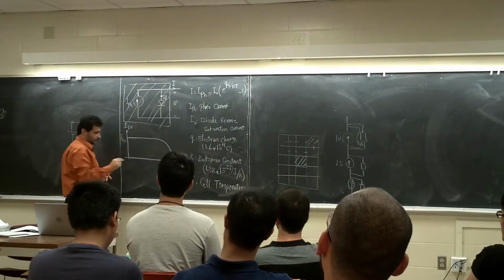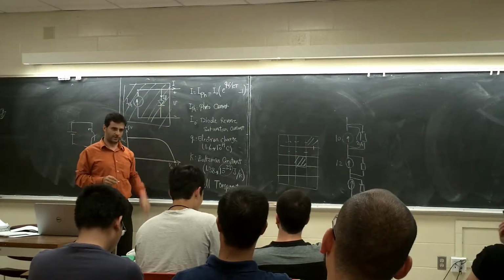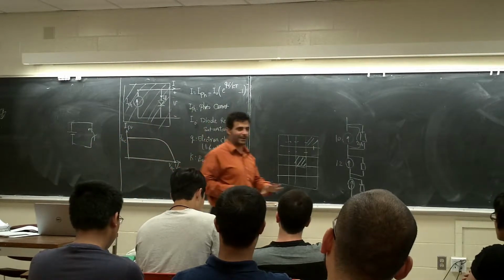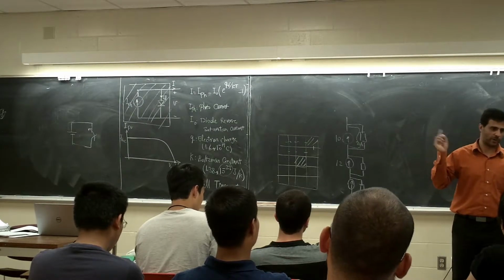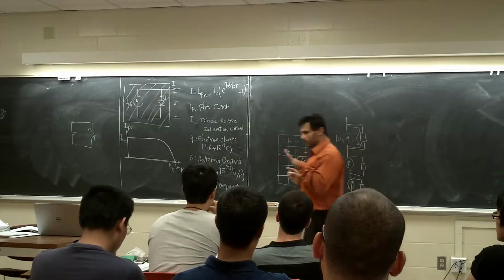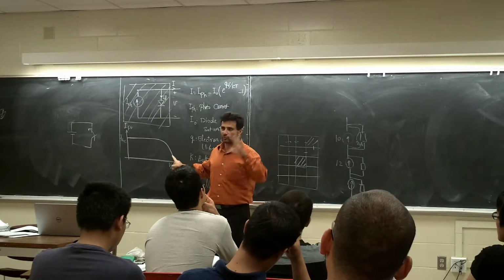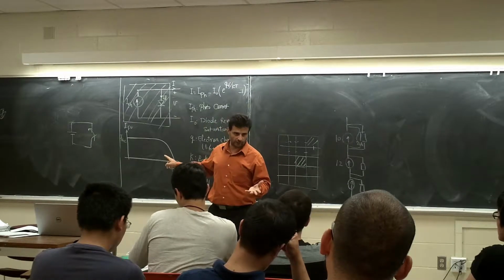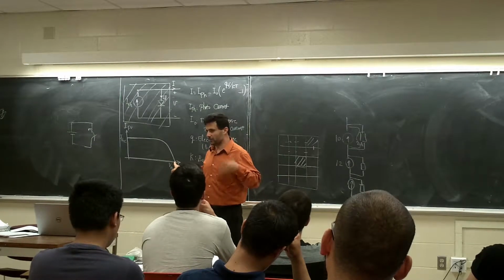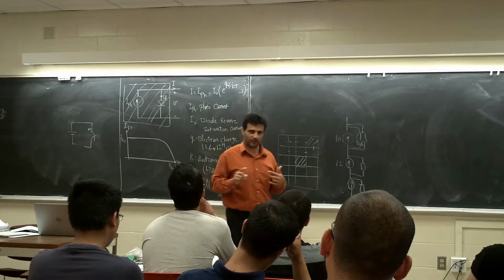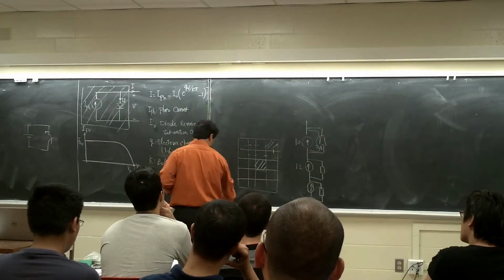So this is the I short circuit. And this is the V open circuit. If you keep it open, you're going to have the maximum voltage. Usually with all these solar panels, early morning, let's say there is no sun, right? So there is no voltage, nothing. But as soon as the sun comes up, you start from here, because there is no power generation yet. At least you should get enough voltage to start generating. So basically you start from here because it's open, right? As soon as you start to operate it, the voltage is going to drop a little bit. We'll tell you why it drops, because of the MPPT. But there is a VOC and there is an I short circuit.